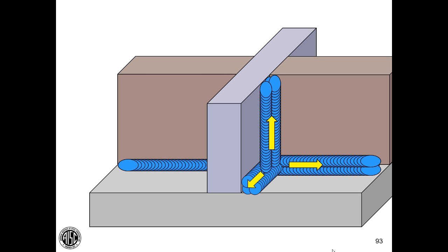And I hope you can see sigma 1 equals sigma 2 equals sigma 3. And if you see that, then you recognize that at this point, the inherent ductility of steel is simply not going to be exhibited, and I'm more likely to get brittle fracture from this location.